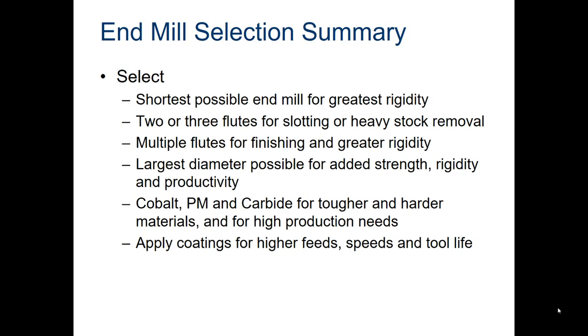You also want to use your largest diameter. So whenever you're cutting, if I could do the same job with, say, a 1/4 inch versus a 1/8 inch, I'm going to want to pick that 1/4 inch, because it's, again, going to have less vibration. It's going to be more structurally sound. And so you're going to get a better dimensional tolerance. It's going to be a more accurate cut that way, because it's not going to vibrate as much. And so that's what we want. We always want to use the largest tool that we can for whatever job we're doing. Some jobs you just have to use small tools, but if you can use a bigger one, that's what you're going to use.